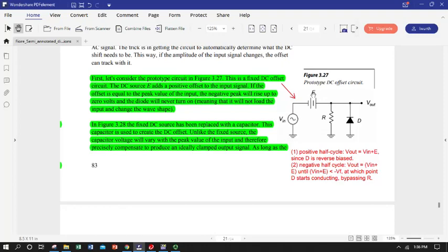Okay, so E is positive, so we're going to have a signal, basically a negative going signal, and you can kind of think about it as running back through ground, because ground is typically connected, as we find out with our grounding loops. So we're going to have a signal on this side that's going to exceed whatever E is giving at this point by the forward bias voltage of the diode. So we're really going to have to apply quite the negative signal of V in before we can open the diode and allow current to flow the other way.